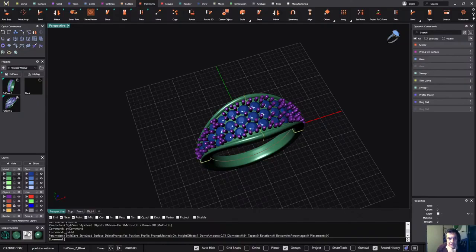I see that Jane was asking why not just eliminate all of these points. It's true, you can eliminate these points, but it's always good to keep the same points between the different profiles that you have, so then the surface is more accurate. And I always like to put extra time on that and not have problems later on.